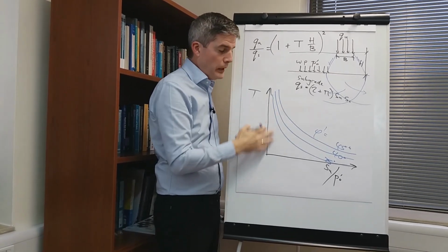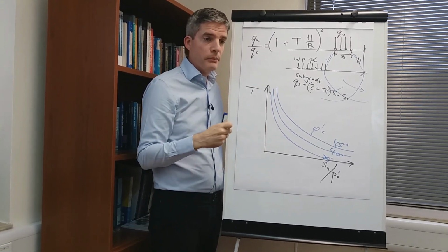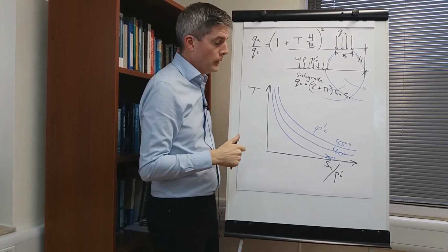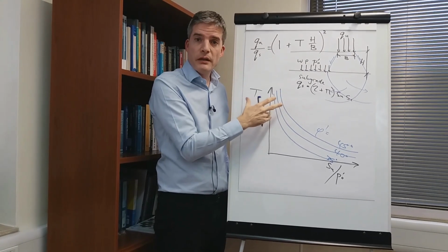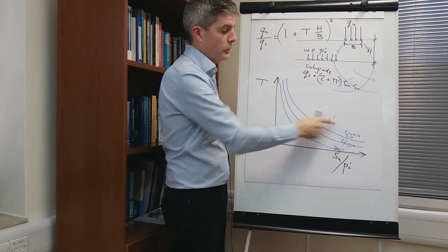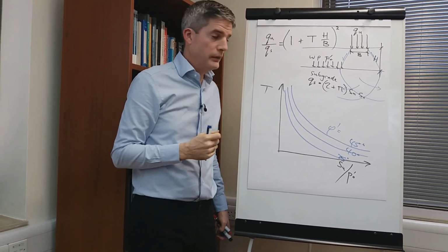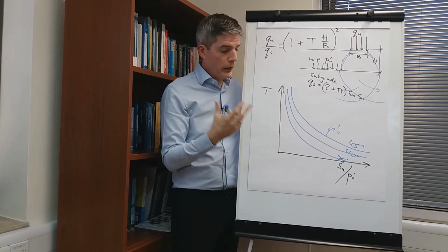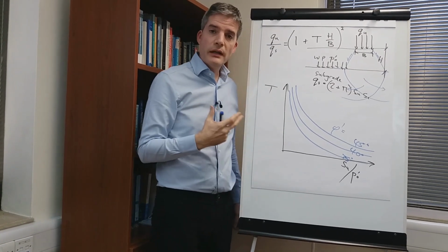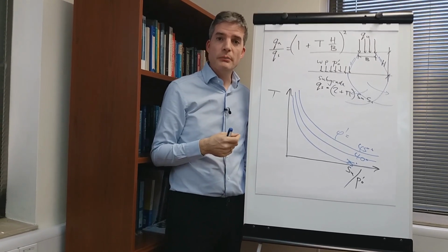It's been derived by extensive numerical analysis and parametric studies, but validated by centrifuge model testing and by full-scale physical testing. This method also allows us to introduce the benefit of mechanical stabilization with GeoGrid products. We will be able to put another design line on here after doing the same numerical analysis and full-scale validation. So there you go, an easy to use but rigorously validated design method for working platforms that allows us also to introduce the benefit of mechanical stabilization.